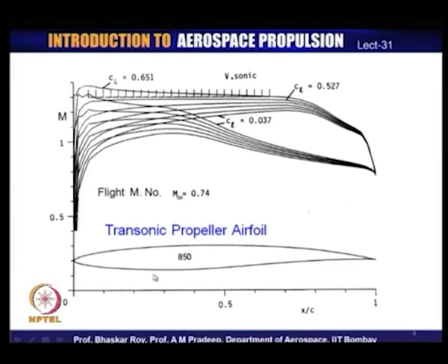So, on the surface of the aerofoil, the flow would actually go supersonic, even though the entry Mach number here is high subsonic, and hence these are called transonic aerofoils. Somewhere over the aerofoil shape, the flow would indeed go supersonic, and as shown in the diagram here, it is most likely to again come out with a subsonic profile. So, somewhere on the blade surface, the flow transits from subsonic to supersonic, and then again transits back to subsonic and leaves the propeller blade subsonically.